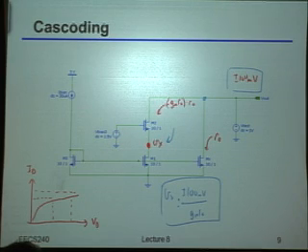Now, to go back to this earlier picture, the reason that's important is that if we've reduced that swing by gm*RO, now I'm only applying this much swing in the drain voltage on that bottom device. And of course, if I have a lower swing in the drain voltage, then, and I apologize for the bad picture, it's a little bit small, for a smaller swing on the drain voltage, obviously there'll be a smaller change in the drain current. Does this make sense to everybody?